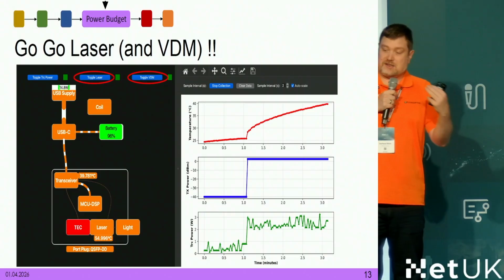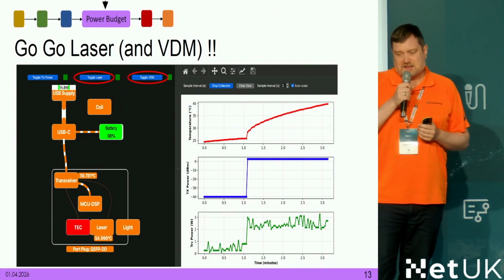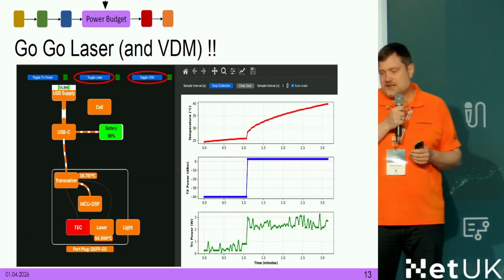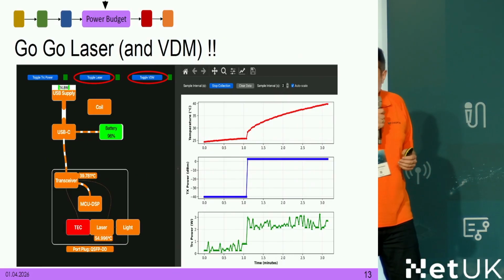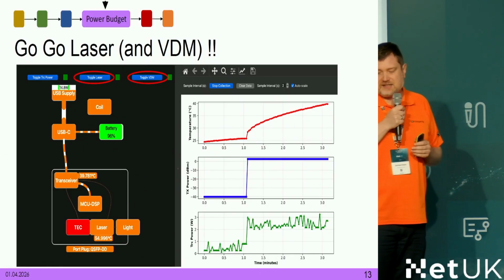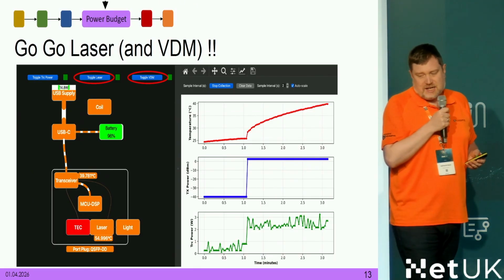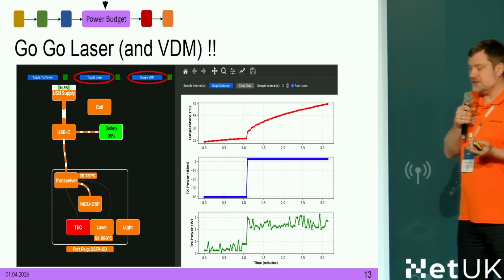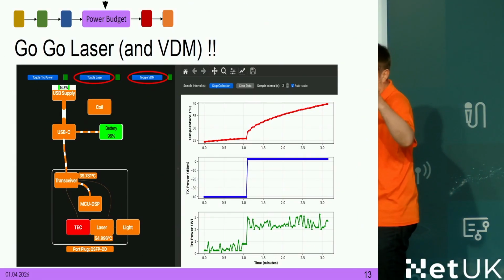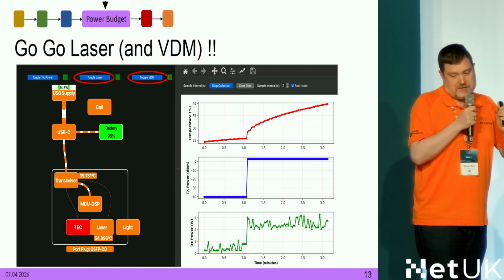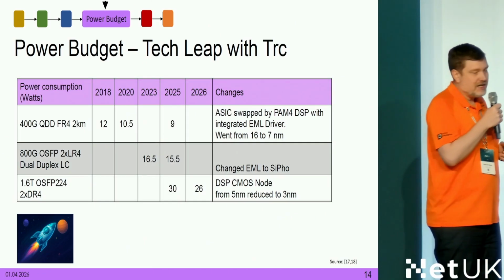The temperature continues rising, and that's another thing that you have to observe. You have to cool down these devices, and now we are at full power, at 3 watts, more or less for this transceiver. It's a normal operation, right? And now you can see the difference here between the normal temperature of the whole transceiver and that laser temperature, which is inside that dedicated chamber.